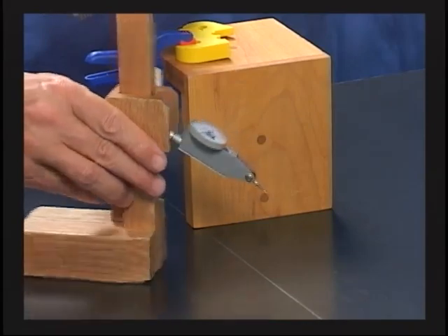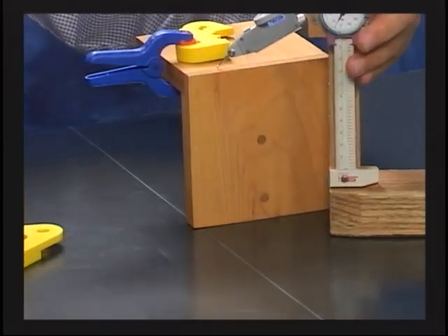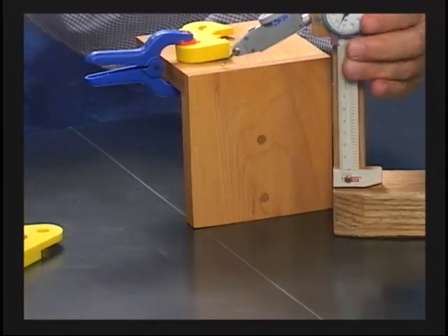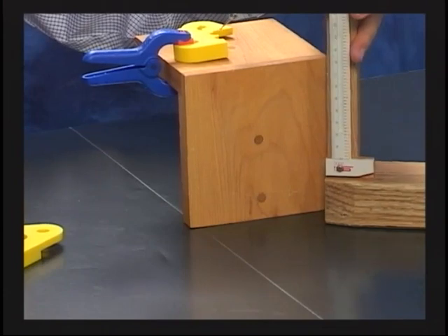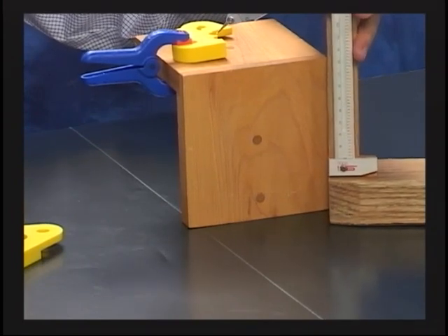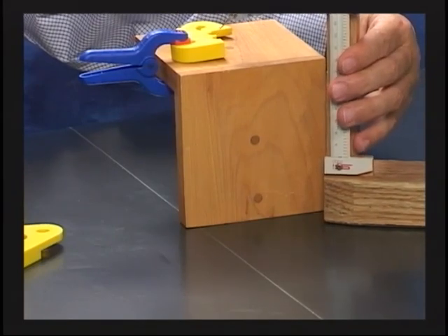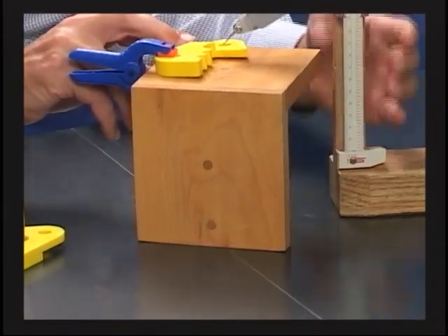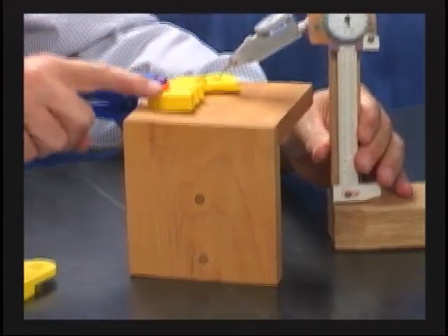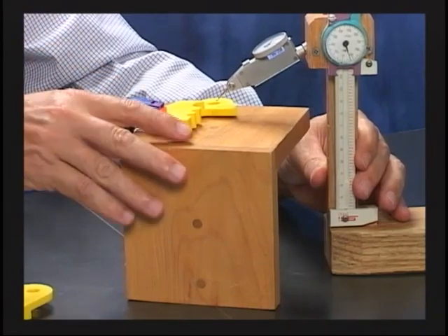You see with my height gauge here, I set it up. I can get my 0 off the plate. Remember all those dimensions? Remember where we were checking this surface here? I think that surface had to be within 500, and it had to be a plus or minus, not a plus or minus, but a profile of 4. Then we came over to this surface, and we were indicating this surface. That had to be within a zone. See what I'm doing is I'm resting on the high points. I'm coming to see if that falls inside of the tolerance zone.